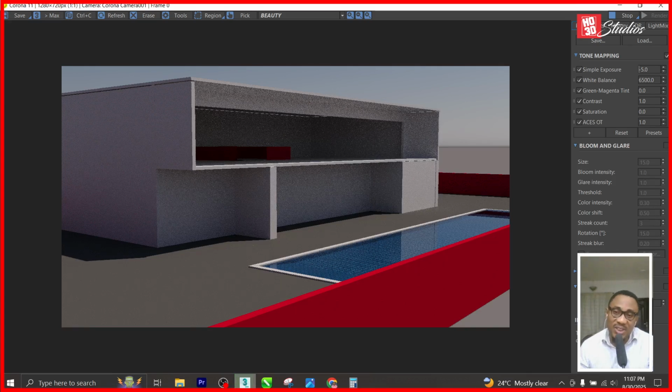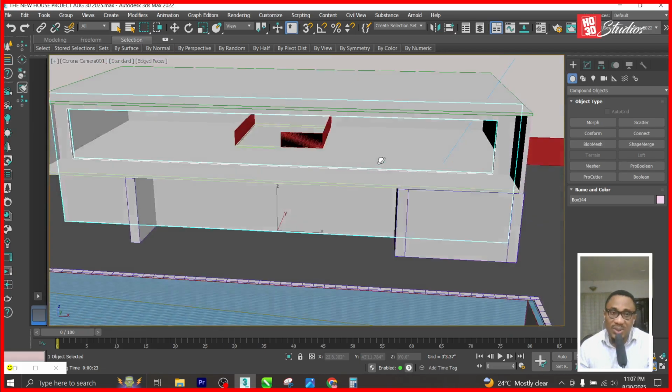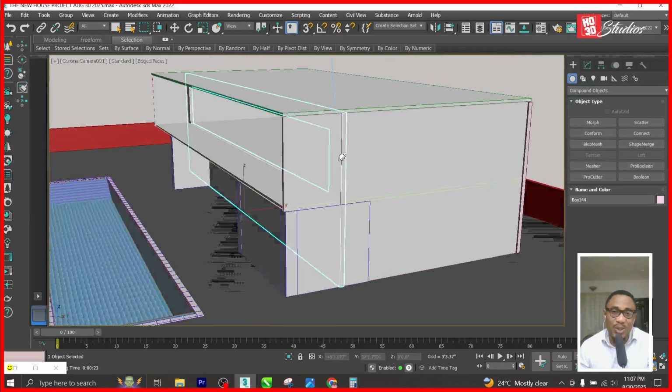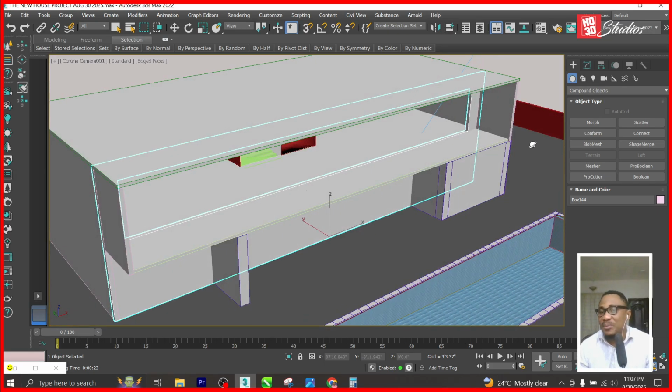balcony. So what this does is that this roof, because this is protruding beyond this wall, no, I think I should go back to the 3D. This roof is protruding beyond this wall, so it naturally casts a shadow into the room. So the inside of the house is cooler than the balcony.